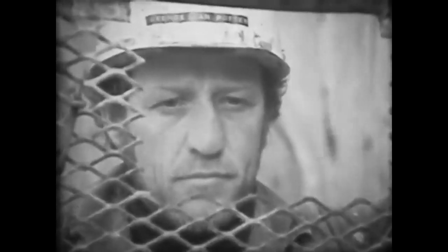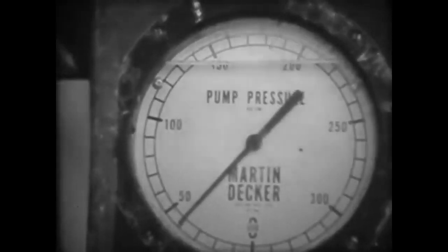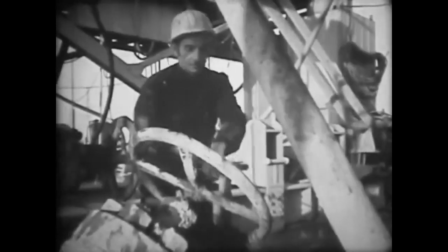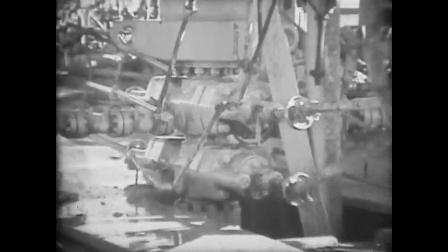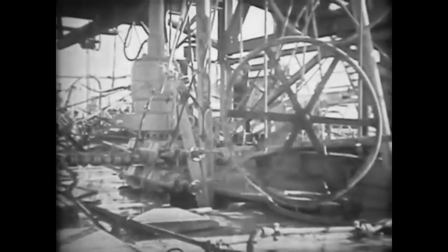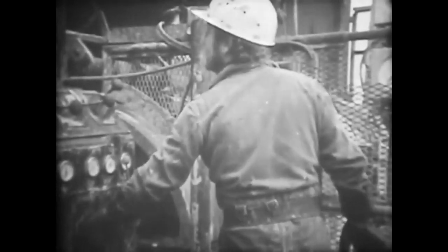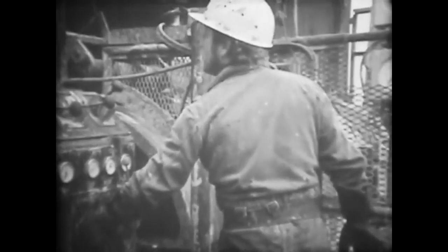Mechanical troubles don't happen all that often, but on every well, you have to be prepared for hazards of another kind that may lie buried in the rocks below. A sudden increase in mud flow from the well. Stop drilling and close the blowout preventers. Everything shut down. The pressures are measured, and the pumps are restarted slowly while the cause of the flow increase is identified. We've encountered high-pressure gas trapped in a shallow sandstone.